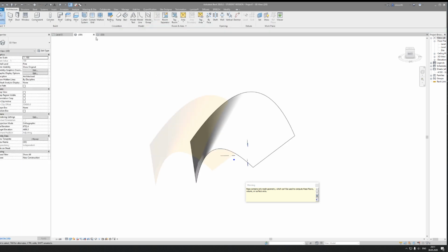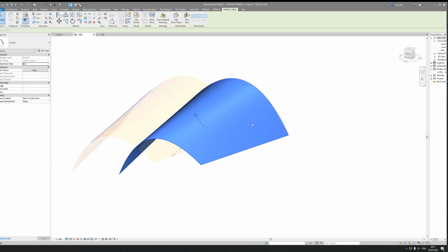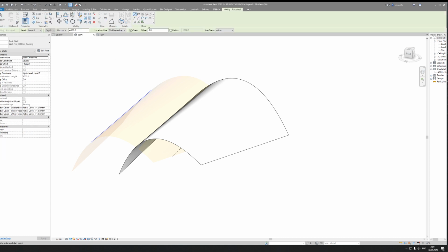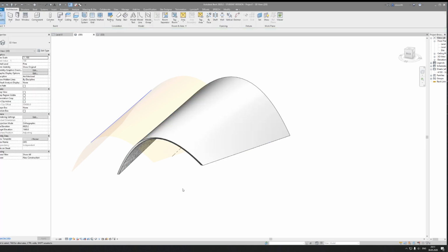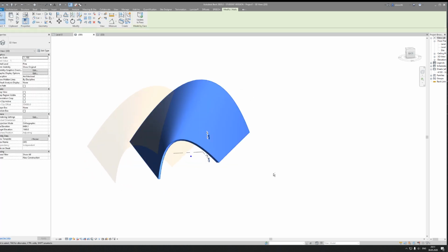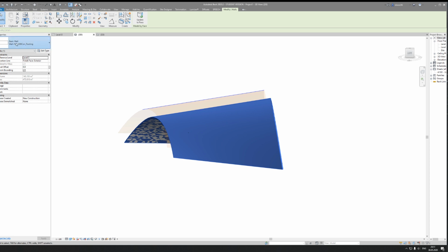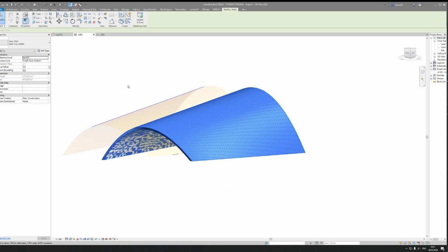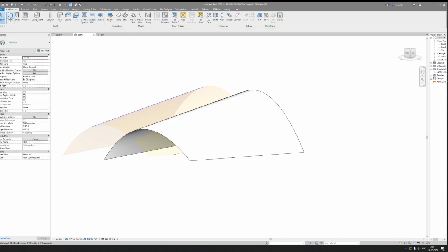As you understand, if it's a meshing form, what can you do? Yes, you can place, for example, where's my ceiling? Oh, not ceiling, sorry. Where's my wall? Yes, and now I can use it like a wall. As you can see, here is the wall. It's real geometry, and I can change it. Maybe I don't want this wall. Maybe I want to create, for example, a curtain wall.